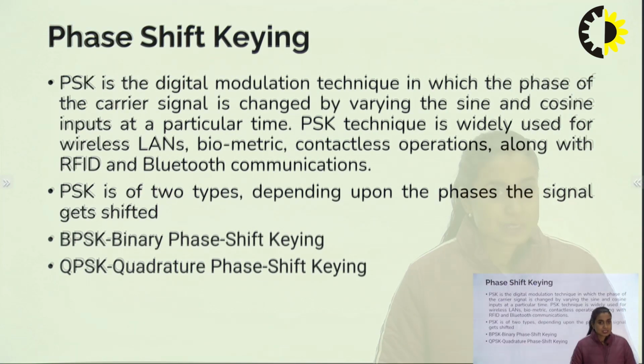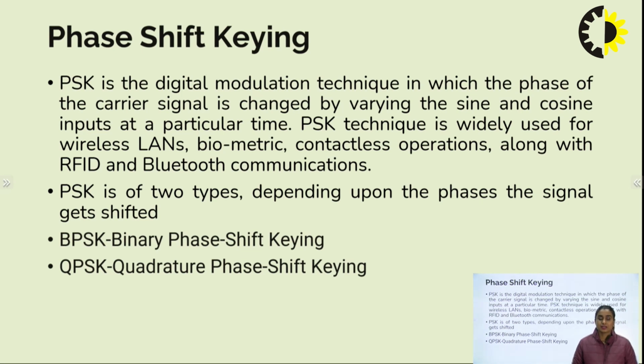It is abbreviated as PSK, and PSK is a digital modulation technique in which the phase of the carrier signal is changed by varying the sine and cosine inputs at a particular time. It is widely used for wireless LANs, biometric, contact lens operations along with RFID and Bluetooth communications. If we see our digital TVs as well, there we could easily see that it also uses 16 PSK. So it has many applications in our day-to-day life. So study of PSK is important for us, right?